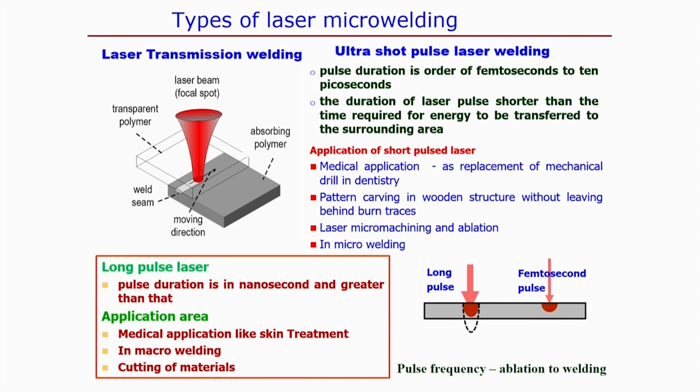Normally, ultra short pulse laser welding is analyzed using non-Fourier heat conduction or two temperature models, assuming there is phonon and electron coupling, or scattering between phonon and phonon. Based on those principles, we can estimate the different relaxation times when a substrate material interacts with an ultra short pulse laser, that means any femtosecond pulse laser.